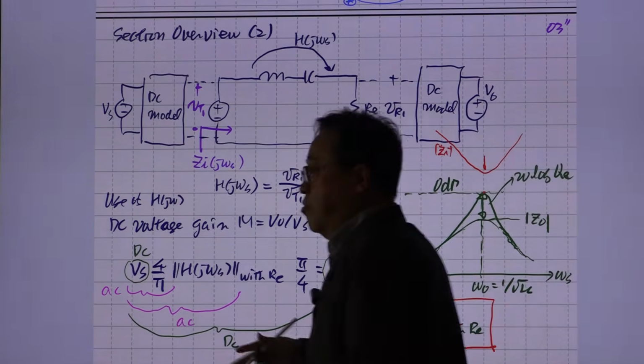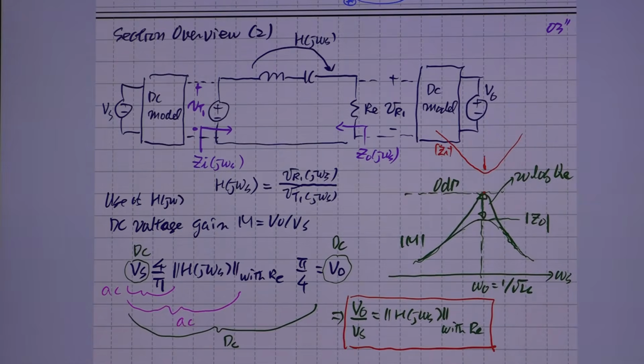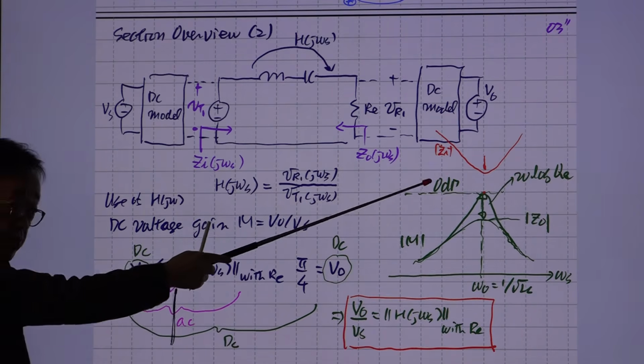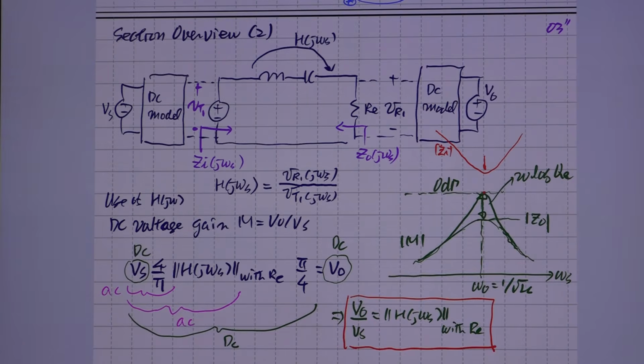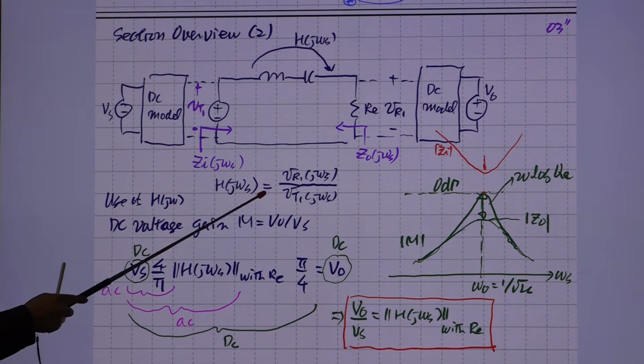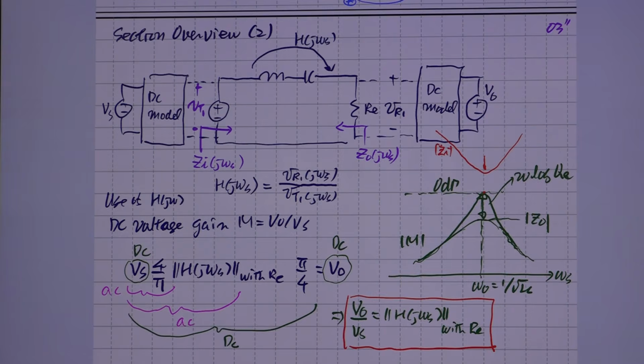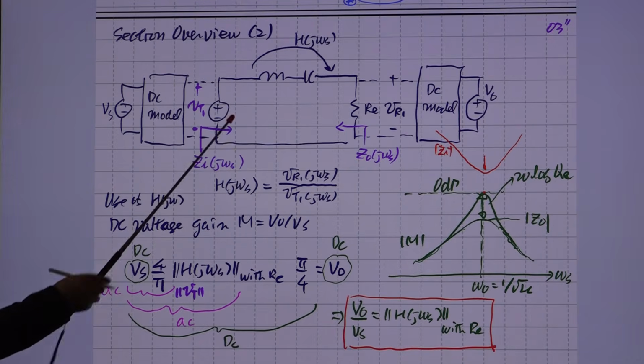First we want to evaluate the DC gain from input to output. So DC in is the input of this gain M, and this is the output. There is an easy relationship between these. First, this is the input, Vs, right? If you multiply Vs by this number, 4 divided by pi, this is Vt1, the magnitude. So this will give you a number. This number is Vt1 magnitude. This is an AC waveform, so the magnitude of AC appearing here is this one.